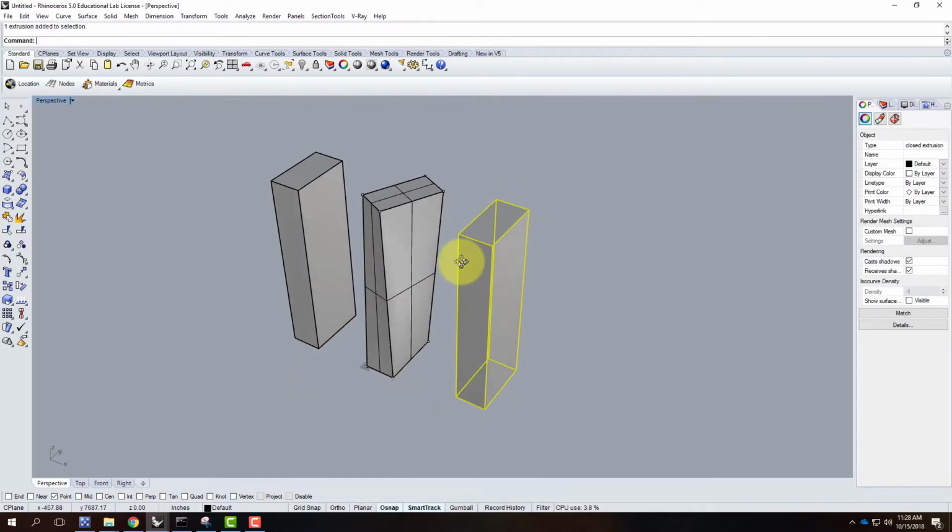And I'm going to use something called a cage edit. What a cage edit does is it essentially puts like a wireframe cage around your object and lets you twist and manipulate whatever's inside. In this case, the cage is going to look an awful lot like the building. But I could have some kind of a little rubber ducky inside a cage, and I could tweak and pull it, and it would do the same kinds of edits. So it doesn't matter what's inside the cage. It's just the fact that we're transforming what's inside the cage using this cage edit command.